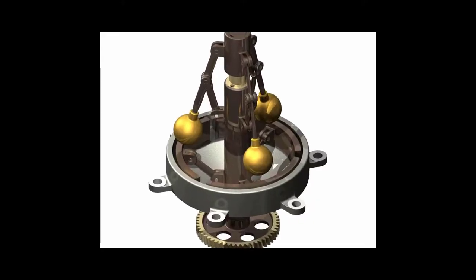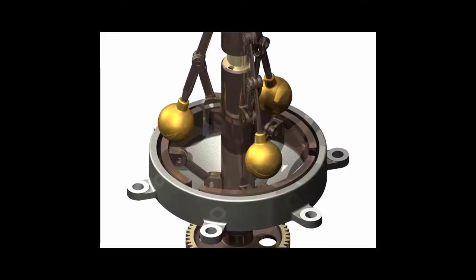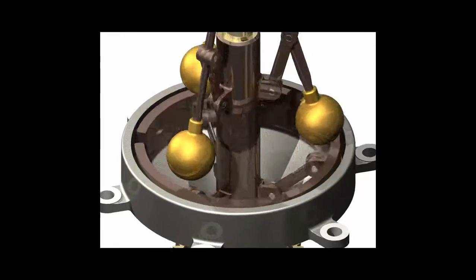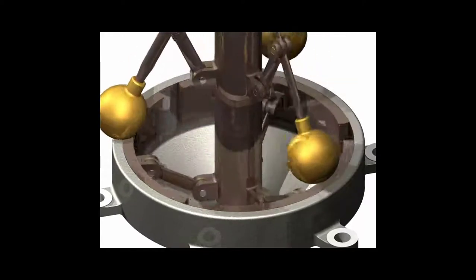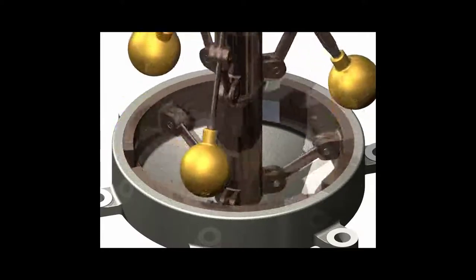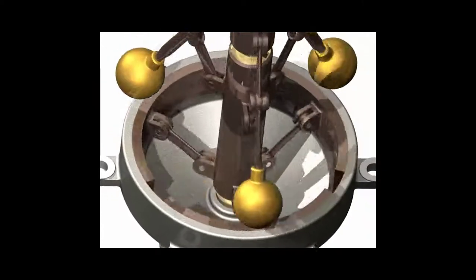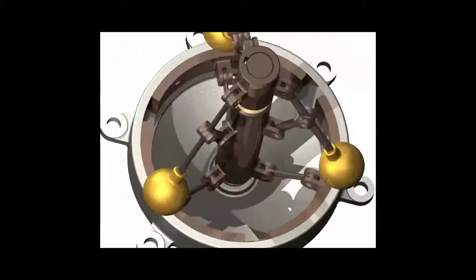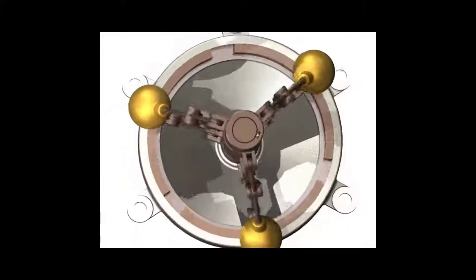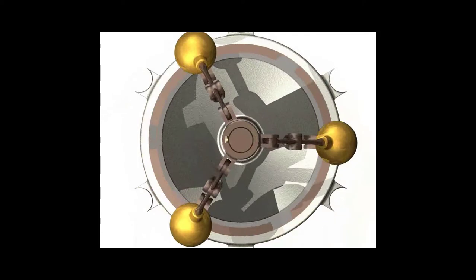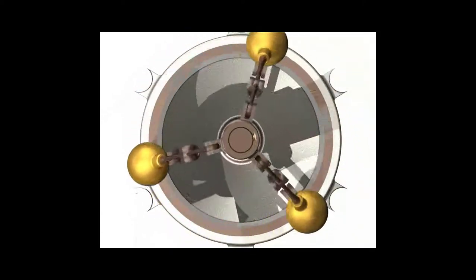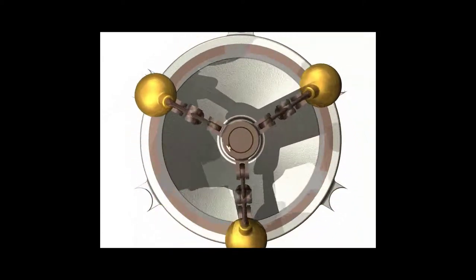At first the balls fall down due to gravity, then the central subassembly begins to rotate and, as you can see, produces the contact of the sabots with the drum. This contact will stabilize the speed of rotation.